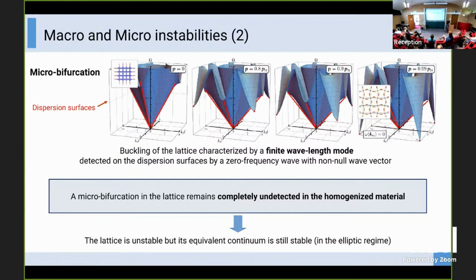I think what I would translate from dynamics, band gaps, to the source of stability, is low frequency band gaps near the local resonance. Maybe if I translate it, there will be some kind of loss of global stability caused by these effects. I think one open question is, we can homogenize at higher order, so obtain a higher order continuum or non-local continuum that can catch this micro-instability. This I think is an open question.